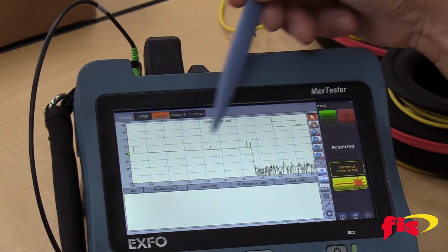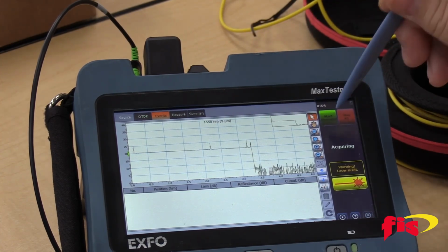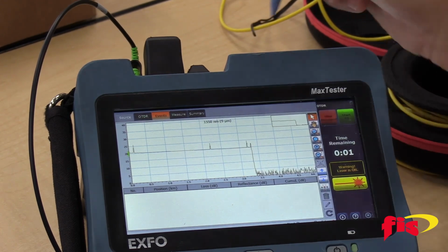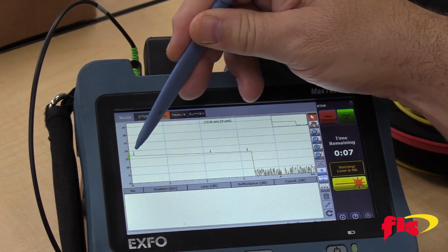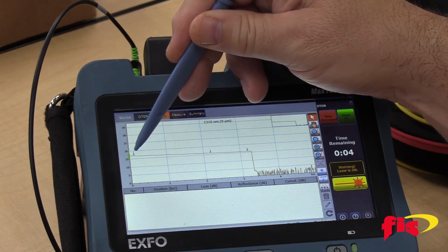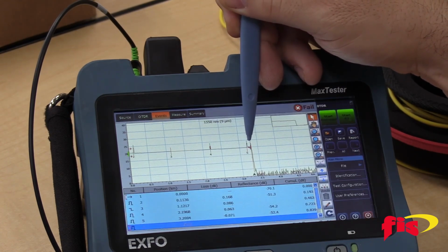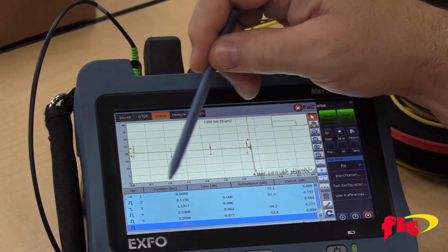So now we can get measurements on the front and back side of our first and last connector. If I do a standard test here, timed, we get about 10 seconds per wavelength, pretty decent for a shorter cable like this. What you'll see is it will now incorporate this second and third connector, right? That's where my test cable meets my launch cable, and the end of the test cable, and then the first connection on the receive cable. And what do we see here?